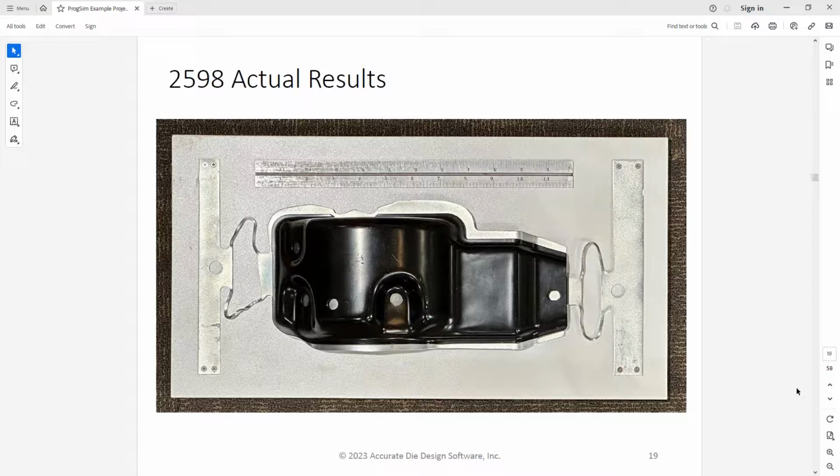And today, this is a great example. Today, there's a big cutout in between this thing. We left plenty of material because that's what the customer wanted us to do. But if the volume was right, you could pay for this die in a couple of years by simply using ProgSim to fully develop this blank and not trim away any of that material in the die. It doesn't need to be, especially for what this part is. So yeah, it changes the way you do business. Next.